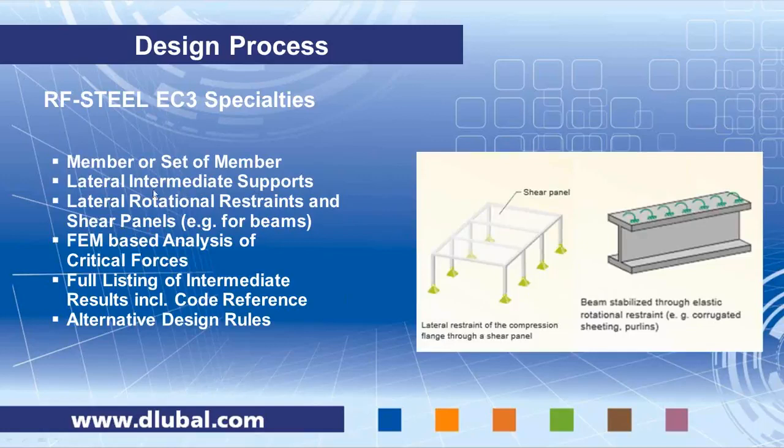A very important feature is the lateral rotational restraints and shear panels. For example, if you have a moment frame for a steel hull and you can take into account the diaphragm that is stabilizing the I-beam against rotation, you can reach much higher critical bending moments, and therefore you get higher critical values and a better design ratio for your stability design, and this is vital in those cases. If you don't have this, the chances that you have to use a larger cross-section are very high.